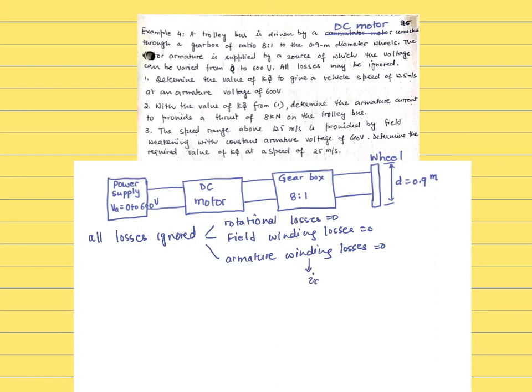Because where is this leading to? IA squared times RA is 0. Now, it is not possible to have this as being 0 only under no load. Otherwise, IA will be non-zero. The other possibility you have is RA being 0. That is possible under all conditions. So, circle it. This is important to us, which we have concluded based on this given statement.